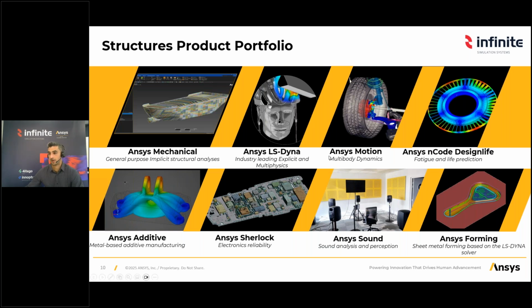Then our second main solver, LS-DYNA for explicit simulations. Also, there are some nice improvements on battery modeling, material modeling, etc. Ansys Motion has also been further optimized, with overall improvements, speed and integration within the Ansys Workbench Mechanical interface. Ansys Sherlock for electronics reliability simulations has been improved with a big focus on thermal mechanical life prediction this year, and Ansys Sound for psychoacoustics improvements.